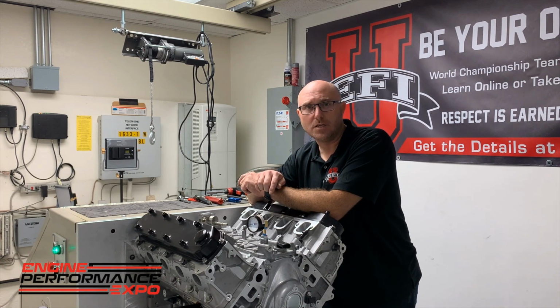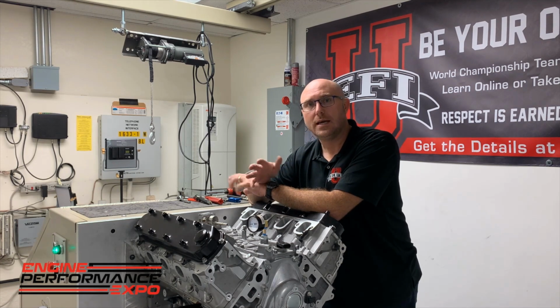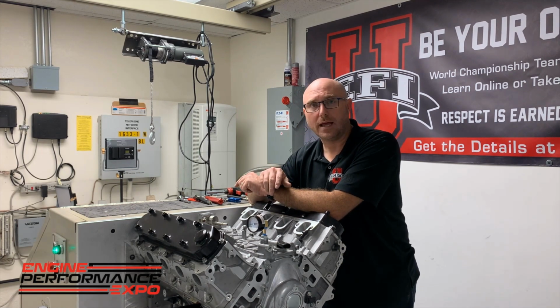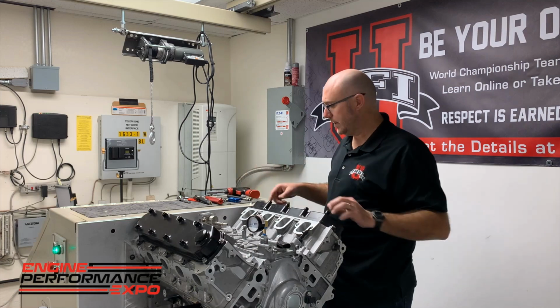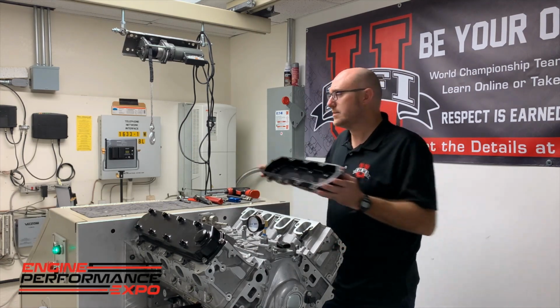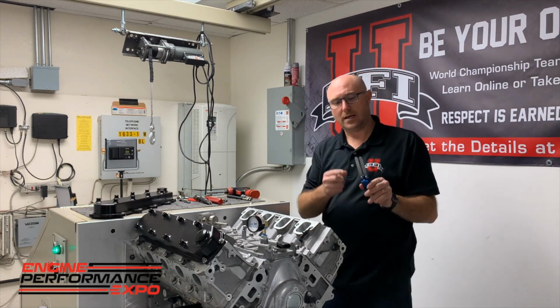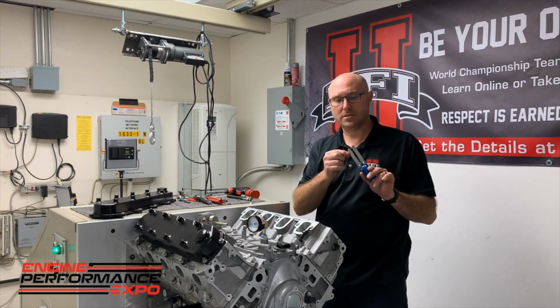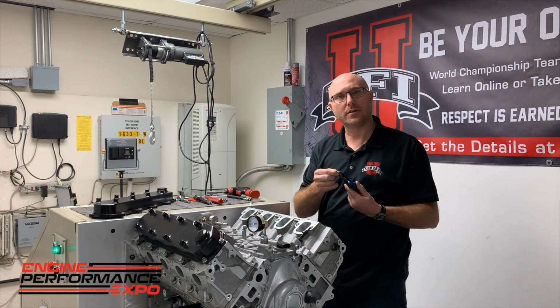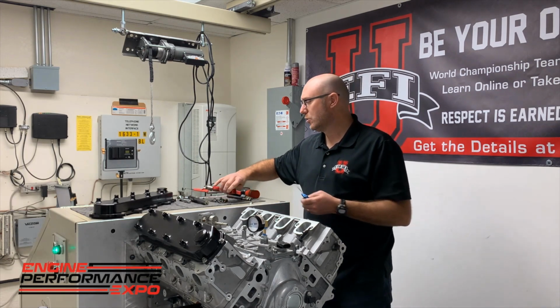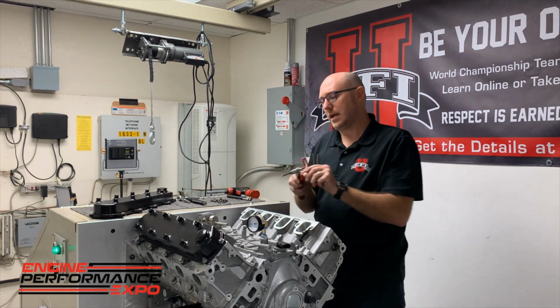But what it allows us to do is run the engine and then stop and take it apart and look at it. For example, I could come over here, I could zip the valve cover off this thing, and then I've got my feeler gauges here. So I got kind of a go and a no-go. This is, tighter than that's too tight and looser than that's too loose. And we've got our torque wrench that we use, and it's got an Allen key in it.